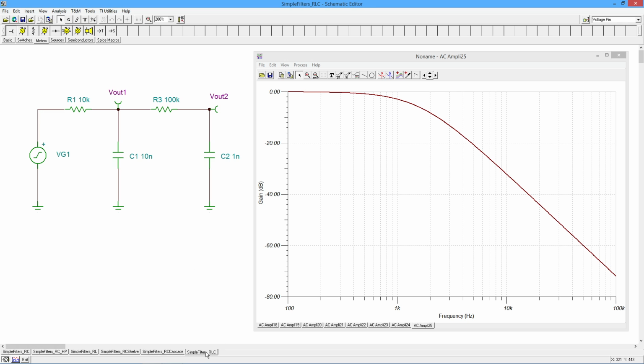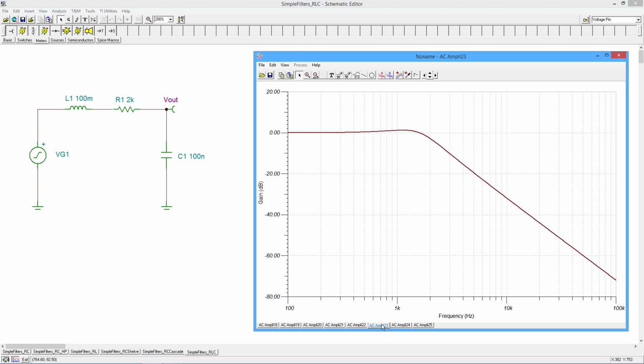But if we do go with the inductor, it's a simpler circuit, and we have a little control over that resonant peak, that area right here. So that's a good comparison just between these two. You can see exactly what's going on. And at the extremes, up here and down here, it's not changing. It's just that resonant peak that's changing, the damping factor of that resistor.